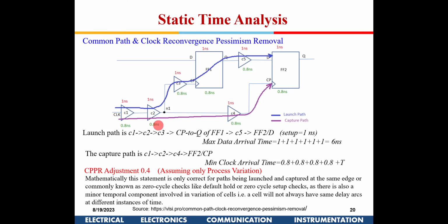The reason is there could be VDD variation, right? There could be a temperature variation, correct? So those variations can come. So theoretically, even after fabrication, this difference can be there. But for today's modern processors which are operating in the gigahertz range, between two edges of the clock it's only a few nanoseconds.